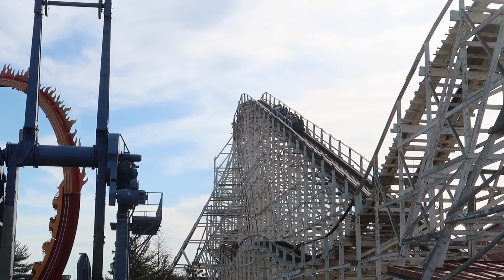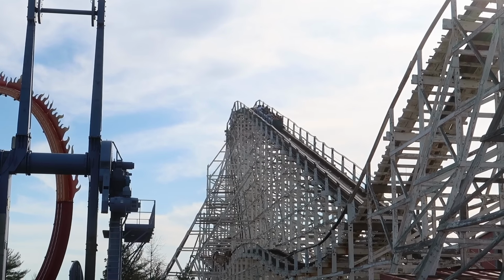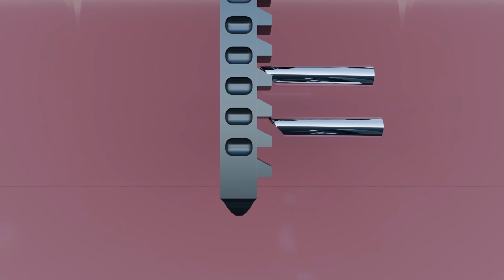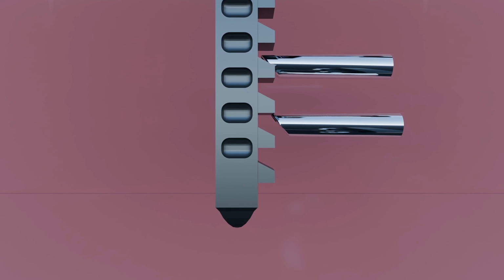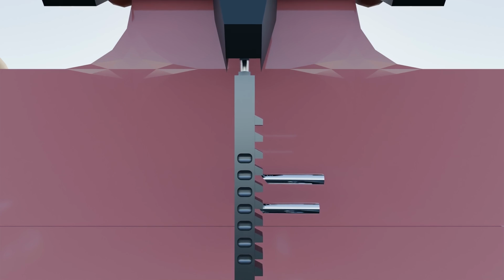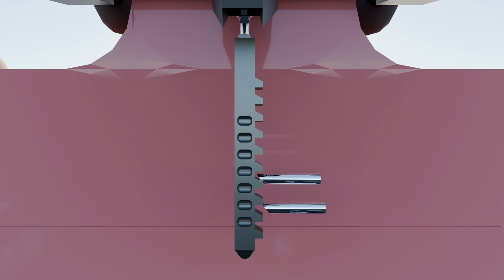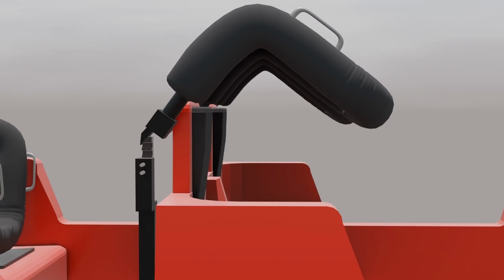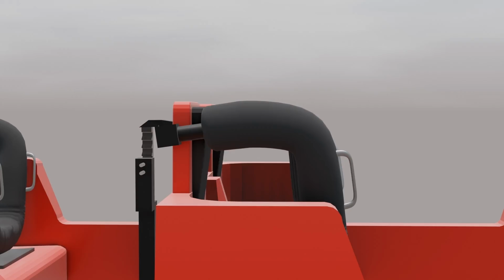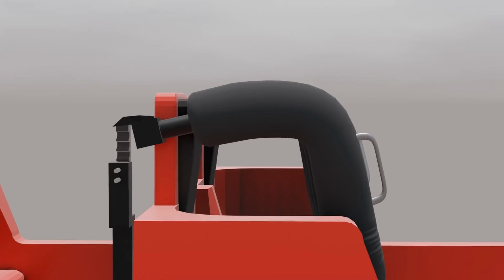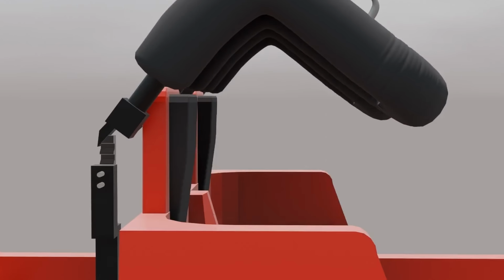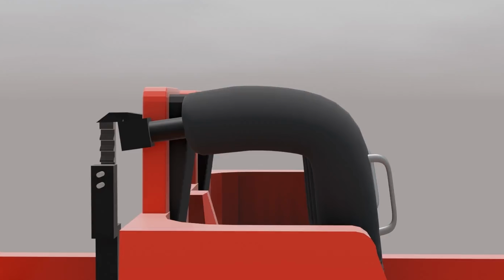This situation can instead be explained by looking closely at the design of some ratcheting restraints. If a ratchet is lowered just past the peak of one ratchet, the pin may be partially engaged with the lower setting. When enough force is applied to the restraint, usually by ride forces, the pin may slip up to a higher setting. When this happens, the restraint pins remain locked, the device was simply never fully locked into that lower setting. This problem can become more prevalent when the restraint ratchets have debris inside of them or are not well lubricated. Regardless, when this occurs, it can result in a rider's restraint moving up several inches suddenly.